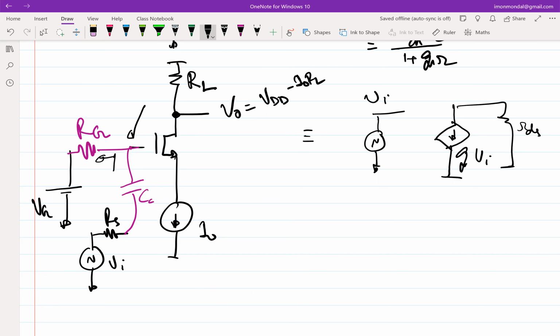Why is it not able to move? Yeah, that's true. That I naught is fixed, but in terms of gate and source voltages, fixed I naught means what? So VGS is constant because the source itself is changing. Correct, exactly, right? So when this voltage is changing, this voltage is also changing itself, right? So it's like a bootstrapping, yanking together, right? So it's going in the same direction. So since it's going in the same direction, it's not allowing any change of current.